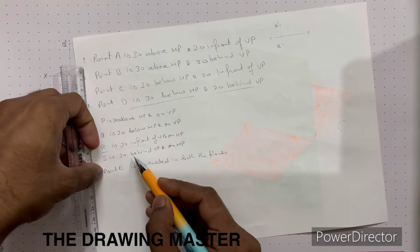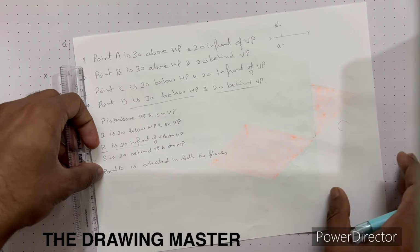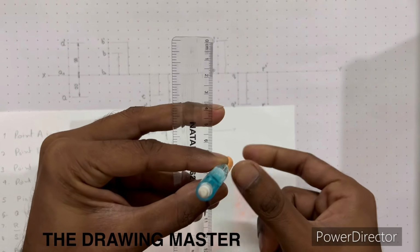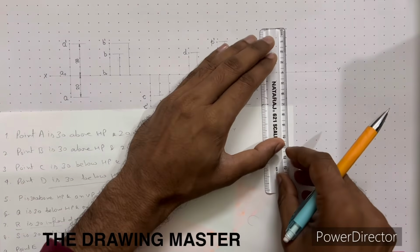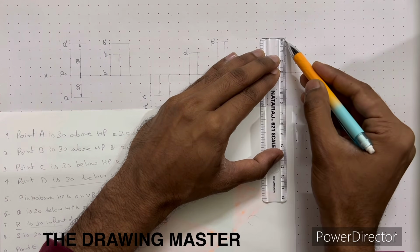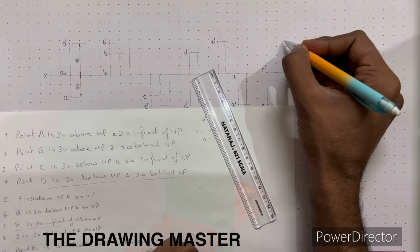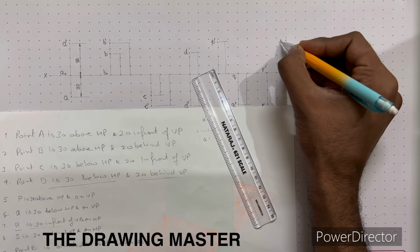Last one is point S is 30 behind VP and on HP. Where are we drawing the behind? After the rotation of the plane, the behind will come upside. 30 behind VP and on HP. Here is the point. Behind is always top view. This is S, lowercase letter without dash.